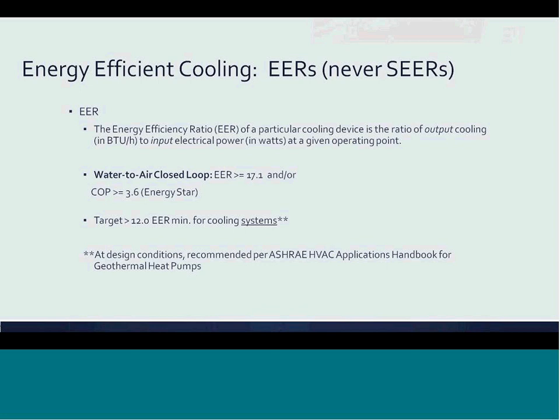You can use the standard rating conditions of different geoheat pumps. This is a way to compare 2 different brands, geoheat pump 1, geoheat pump 2, basically comparing the boxes. For heating efficiency, the geoheat pumps are rated at 32 degrees Fahrenheit entering water temperature to the heat pump. And for cooling efficiency, they are rated at 77 degrees Fahrenheit entering water temperature to the heat pump.